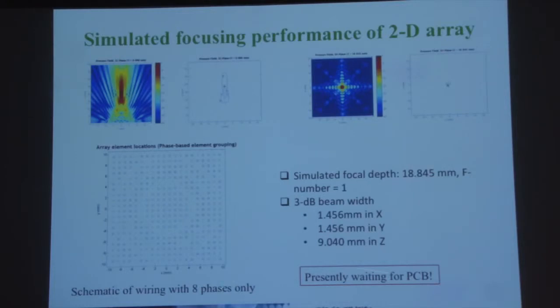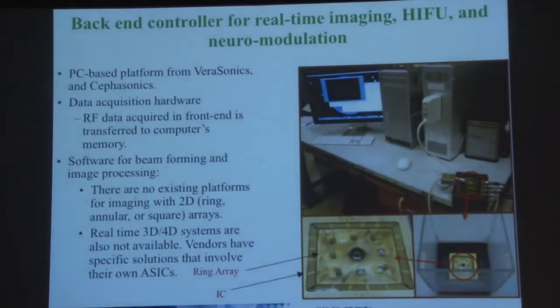We recently sent the PC boards to a company to put solder bumps on these, and once we get the solder bumps, then we will flip chip bond the wafer on top of this, and we'll have a 1 megahertz, either a number of 20 by 20 or the full 40 by 40 2D array for operation. Eventually, of course, you want total control over the 400 elements, so you can HIFU and steer at the same time without the fixed focus that this original implementation will show.